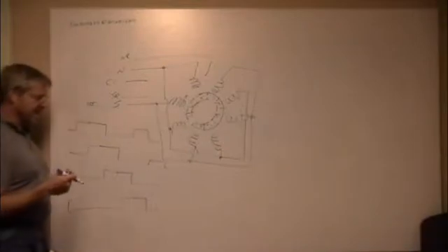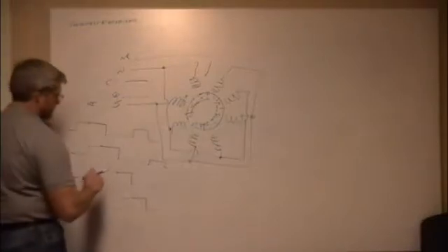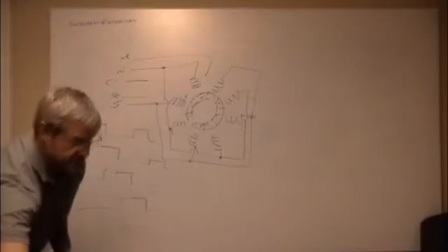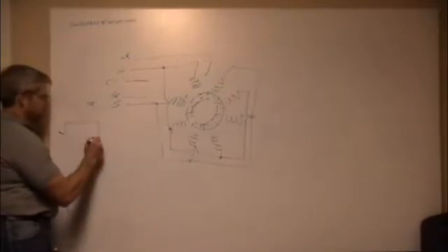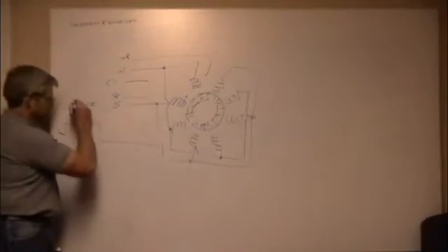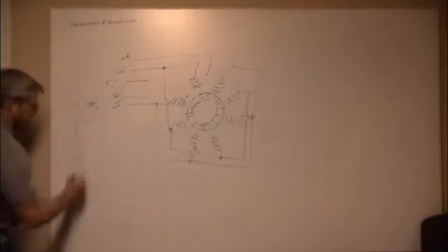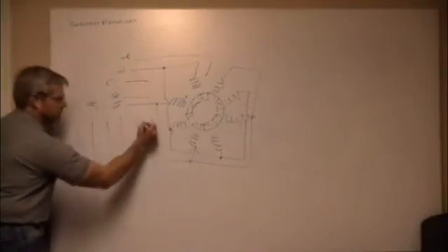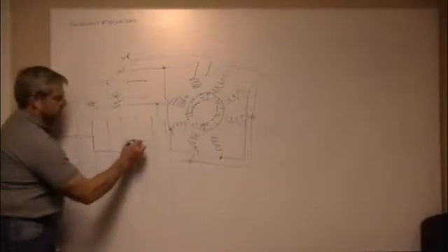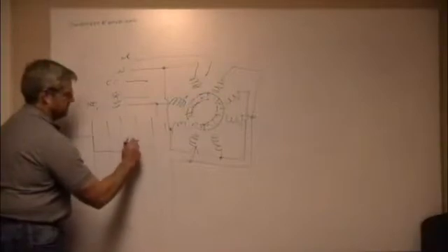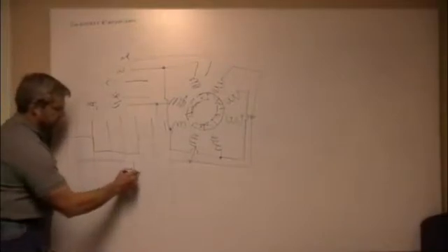And then there's a game that you can play that's called half stepping, where it takes 8 phases instead of 4. Let me do it this way: 1, 2, 3, 4, 5, 6, 7, 8. So he'll come on for 3, and he stays off the rest. And this one, 2, 3, I think looks like that.